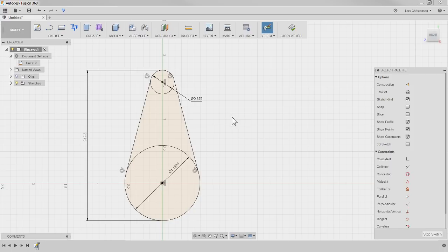So the way I would do this, and again, there probably are other ways to do it, is I would hit alpha line, and I would place a line somewhere over here. And when I draw it out, you will see that right where that line intersects with our tangent line, it shows me the perpendicular icon. You see how it creates that little rectangle right around there when I zoom in? So it gives us that 90 degrees. I can place that line out there.